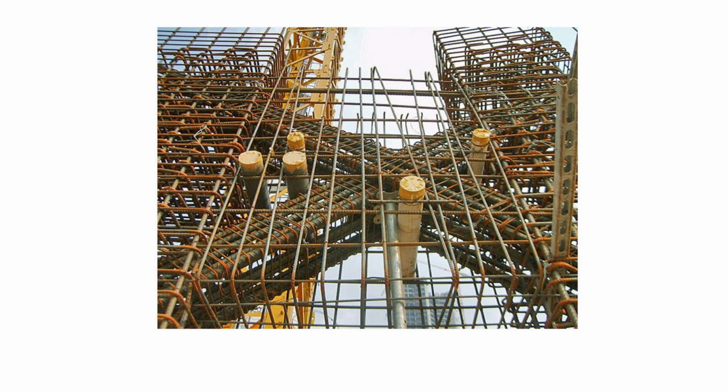However, the use of bracing in concrete structure is unfavorable. As you can see in this figure, the construction of cross bracing is quite tricky in concrete rather than in steel structure. Such a condition will cause difficulty in distributing the concrete mixture equally, hence a high tendency to cause honeycomb.